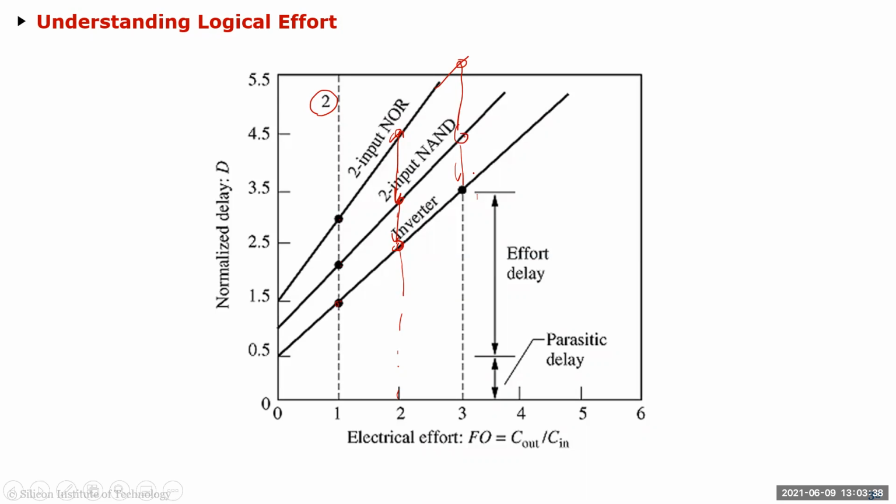So that's why in a design, if it is a speed sensitive design, you want to use a NAND gate instead of a NOR gate, if it doesn't result in an extra path or extra delay. That would give you an advantage over a NOR gate basically.